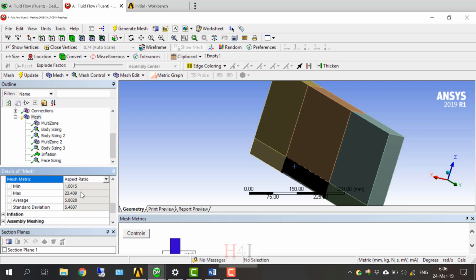In fluid, this is expected near the wall, because we need very fine mesh near the wall, but in the flow direction we don't need it to be very fine. Do you get it? So it is acceptable near the wall to have a very big aspect ratio. So it is relative. I think you can check the location of these cells by clicking on the.